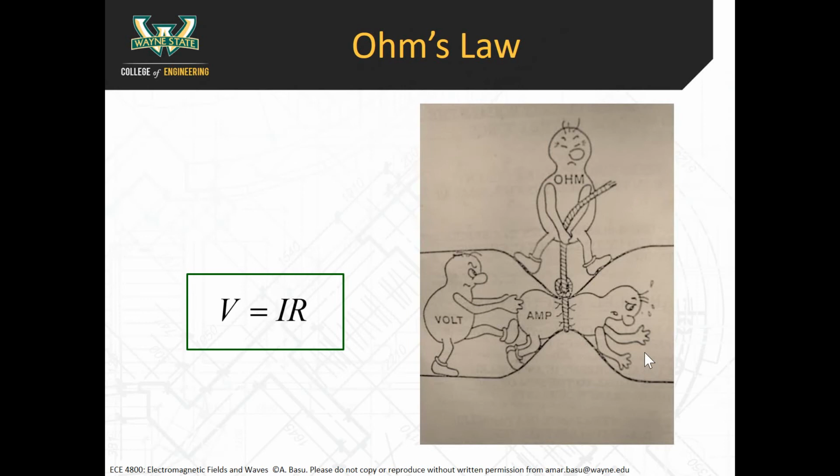This is why in your house, if you know that you're going to be carrying lots of amperage, those wires are pretty thick, right? The ones that are designed to carry like 10 amps, 100 amps of current, those wires are very, very thick. So if you try to apply a high amount of amperage to a wire that's not designed for high amperage, you would actually end up heating the wire and melting it.